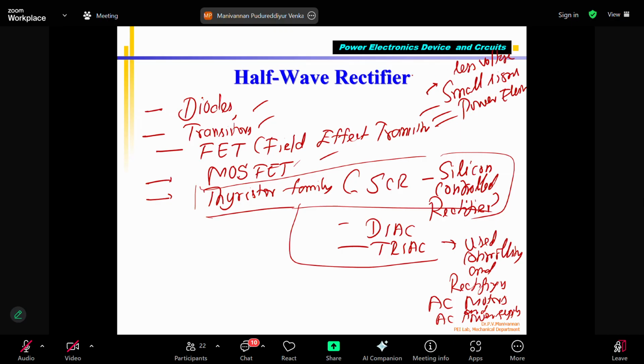Different books say differently: 0 to 30 volts, 0 to 40 volts, or 0 to 24 volts. Some books say 30, generally not very high. If the supply voltage VCC bias voltage is less than 50 volts, you can take it as a small signal amplifier. Many times it can be 10 to 24 also, in some books.